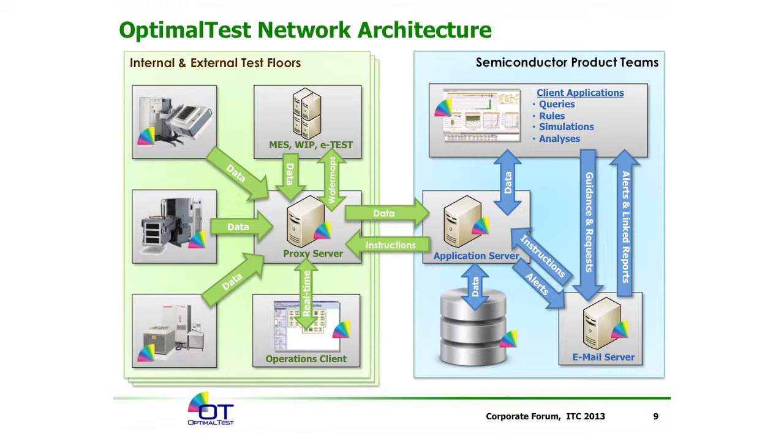So here on the test floors themselves, and again, in the internal or external supply chain, we install a software component called OT Proxy. OT Proxy is a very small software component. It has 2 primary tasks. Its first task is to monitor the tester and collect data log information. Its second task is to interact with the test program in adaptive test scenarios.